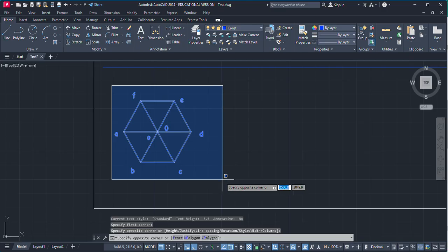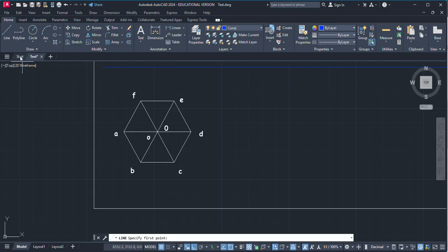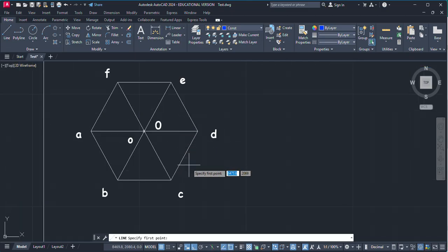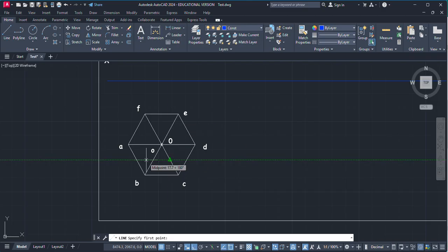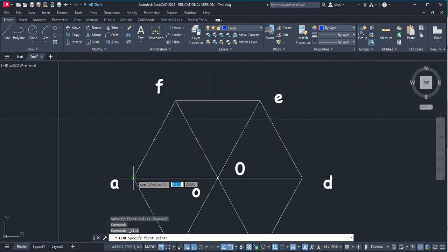Now going to change them to the main drawing. So this is our top view, while our hexagonal pyramid is resting on one of its corners, which is A, and while resting on HP on this corner A, this is our top view. This is our base hexagonal face, and these are slant edges. Now out of this top view, we have to draw the front view for the hexagonal pyramid.